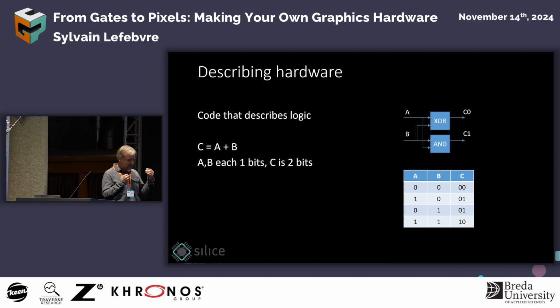So of course, in reality, when you build this circuit, the wires will get a signal inside that is not 0 and 1, but that is ground and VCC, typically 0 volt and 3.3 volts. And in an ideal world, they only take these 2 values. Now, because this is a physical device you're fabricating at the end, this is not as ideal as this, and in fact, things will take time to transition when you change the value from 0 to 1 or 1 to 0.